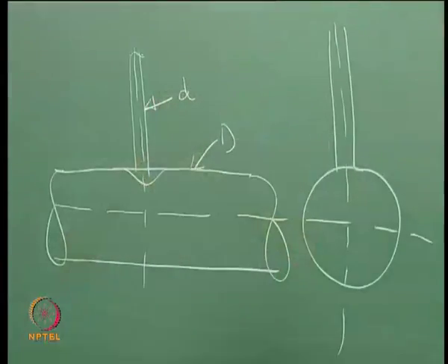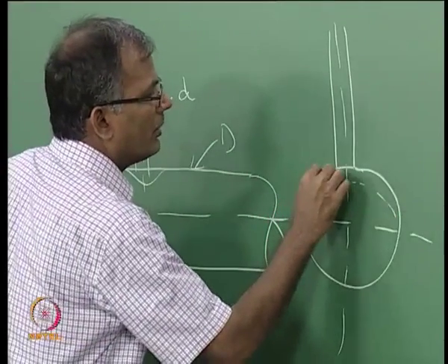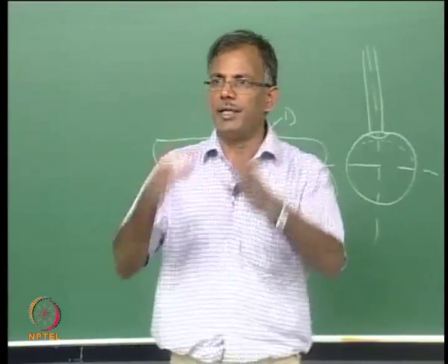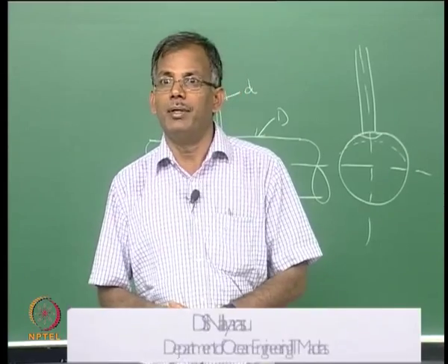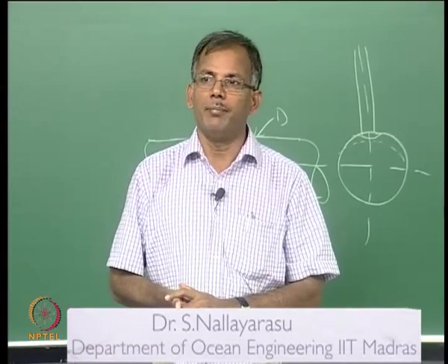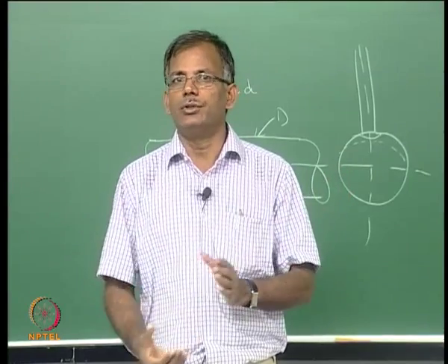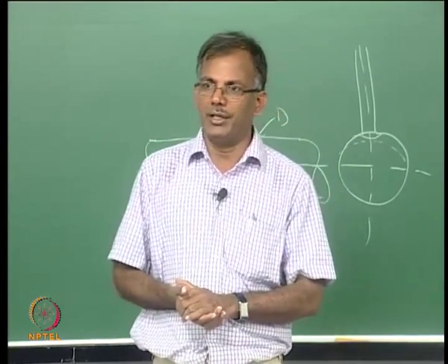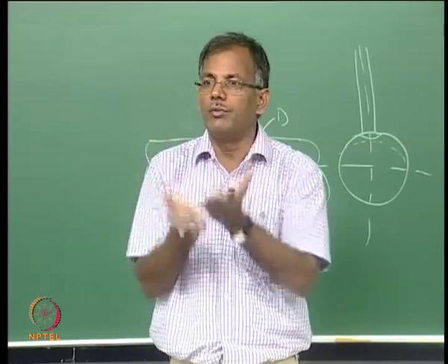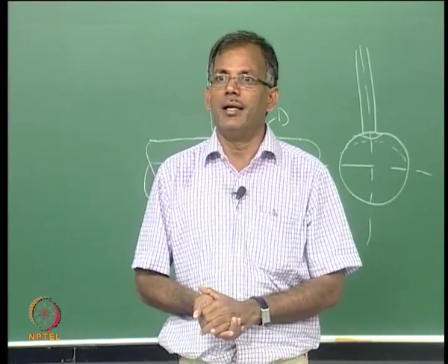There is no chord failure. It is not going to fail like ovalization, because the load is quite small. You might have studied this if you have taken concrete design, punching shear in a column to slab, column to ground slab, or column to roof slab. At a certain distance from the column surface, d/2 distance, you see the critical section for failure by shear, which is called the local punching shear. That means the plate or the slab in that local vicinity is not going to deform, it is just going to go down straight away. Failure is imminent, and which is what we should avoid.